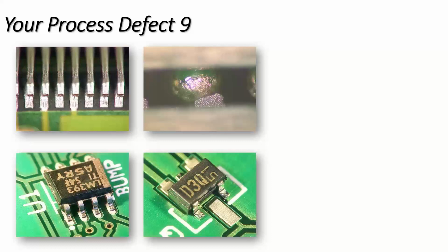You can use SAM, so acoustic microscopy, to look at separation of different layers of components, packages, etc. So that's another technique. The question basically was, what techniques are non-destructive that you can use? So those are sort of two techniques, but wherever you can, try and simulate the problem, and then you can see it, and then you can move on.